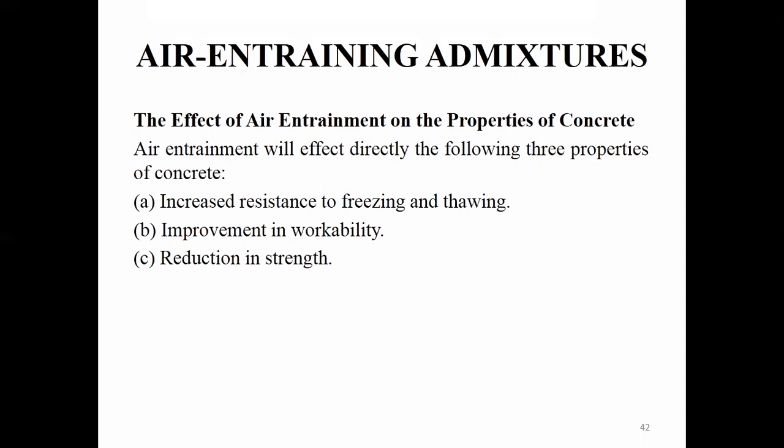Okay, so they have found that placing air entrained concrete having a slump value of 7.5 centimeter is easy compared to non-entrained concrete. Non-entrained concrete means conventional concrete whose slump value is 12.5 centimeter. Can you understand? The slump value is reduced when you add air entraining admixtures.